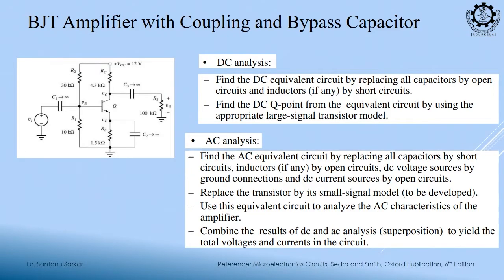So, in the actual circuit, how can we do that? This R1 and R2, we can generate VBB. What is this circuit? R1 and R2, this is termed as a voltage divider. Okay. So, what is my objective? To generate VBB. How can we do that? This is R1 and this should be my VBB. So, what is VBB now? VCC into R1 by.